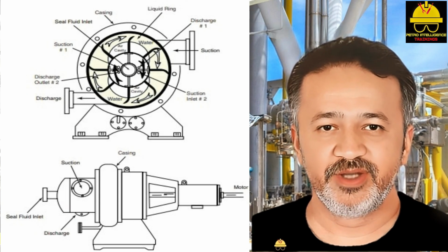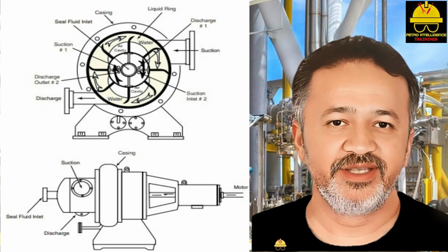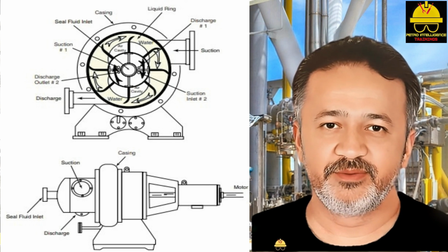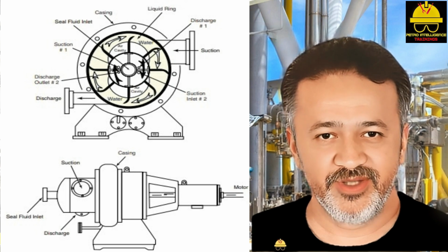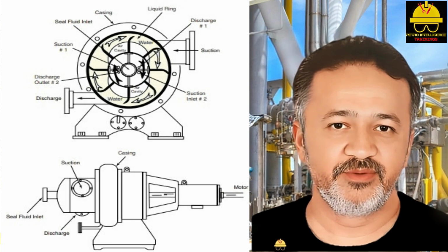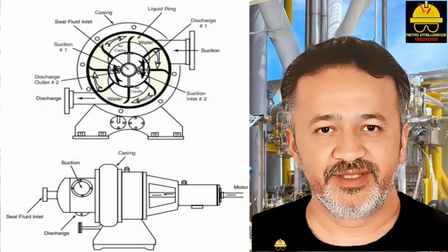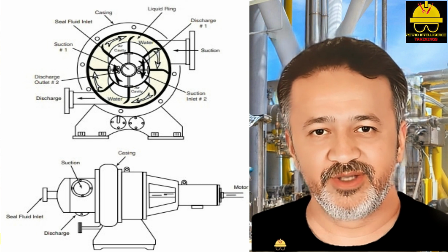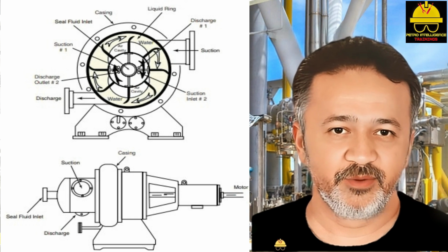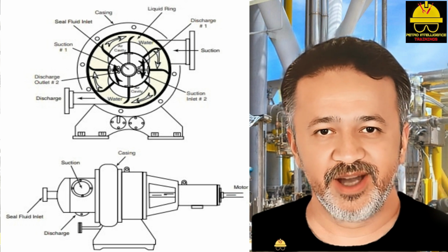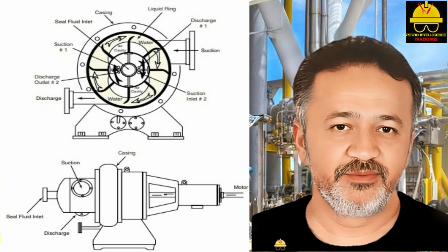As the rotor turns, the fluid is centrifugally forced to the outer wall of the elliptical casing. An air pocket is formed in the center of the casing. As the liquid ring compressor rotates, a small percentage of the liquid escapes out the discharge port. Makeup water or seal liquid is admitted into the compressor during operation. The liquid medium helps cool the compressed gases. The off-center position of the rotor creates an offset in the air pocket.